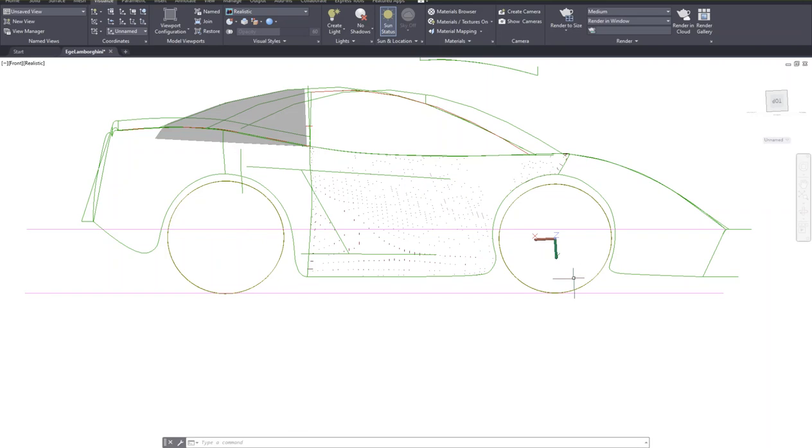I can create the axis, the lines, with the line command, and I can go to quadrants, 12 o'clock, enter, 3 o'clock and 9 o'clock quadrants. As soon as the computer sees the quadrants, it gives me a marker. Now I'm ready to draw my lines.